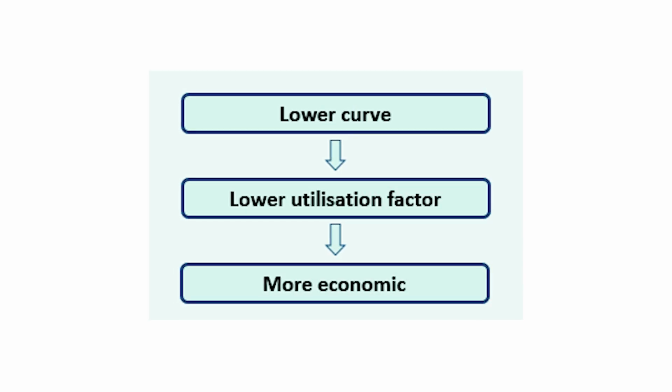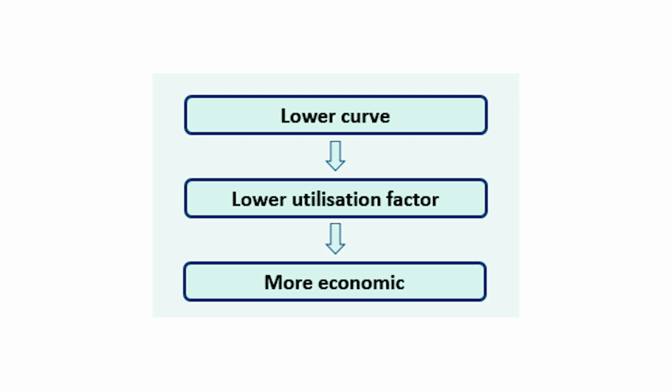The lower the curve, the lower is the utilization factor and the design is more economic. Results and their implications are pertinent to verified glass samples only, and although being indicative, they may not be extended to other geometry and loading without detailed analysis.